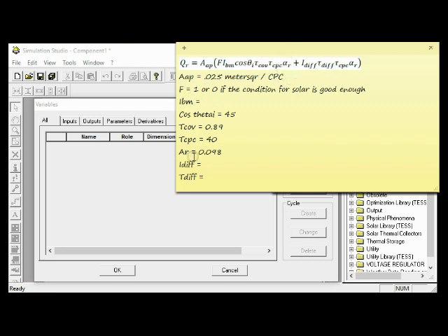And here you can see some of the nomenclatures already have values and some don't. Those that have values will usually be parameters because they are fixed, and those that don't have values are inputs because they are subject to change. Or you might want to fix the value during runtime or attach them to another component within Trnsys which will automatically generate values that will run these ones. So this is the equation, and we're going to model this based on all these nomenclatures and their values, to generate the energy at the receiver.